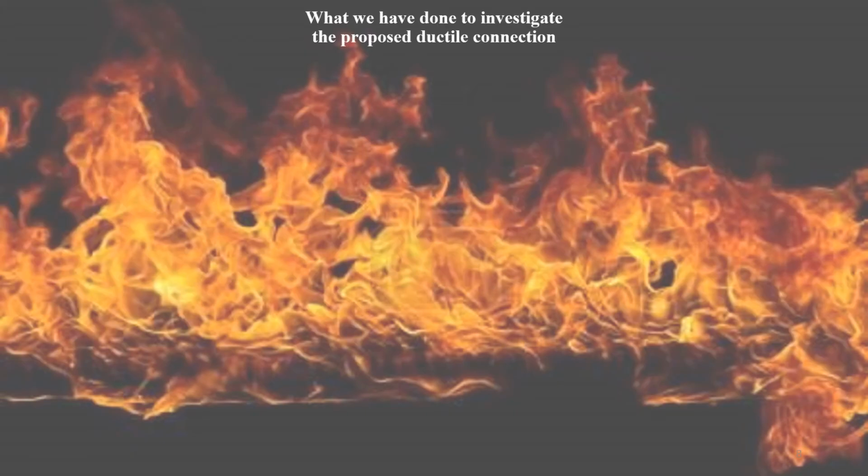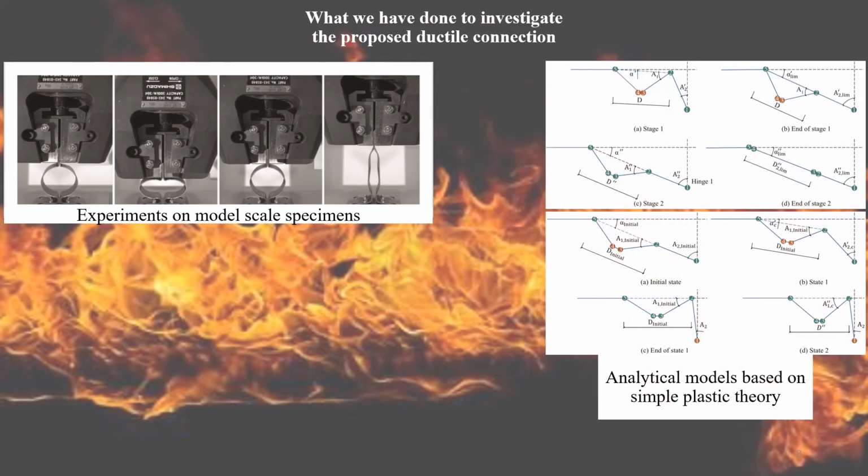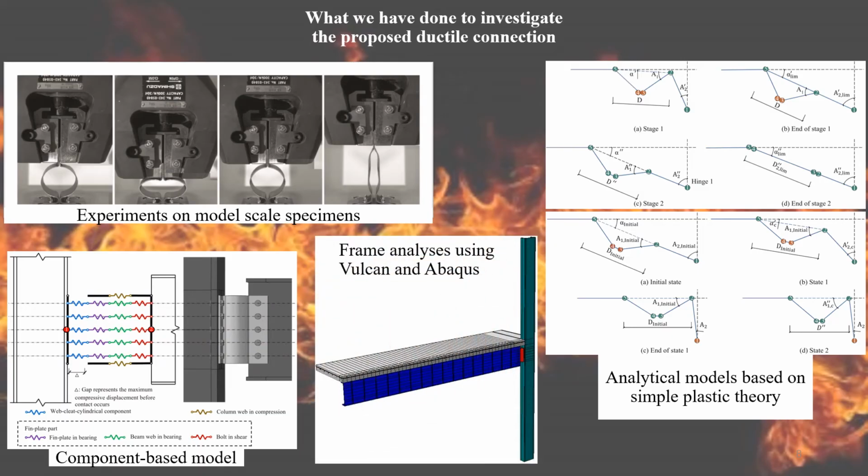Up to now, our research work on the performance of the ductile connection includes experiments on model scale specimens, development of analytical models based on simple plastic theory, development of component-based models, and frame analysis using Vulcan and Abaqus.